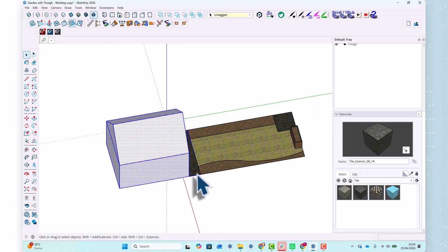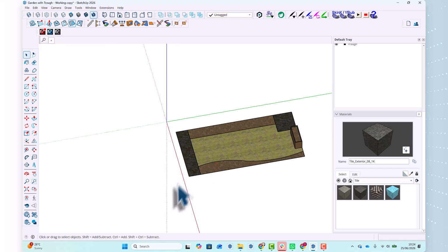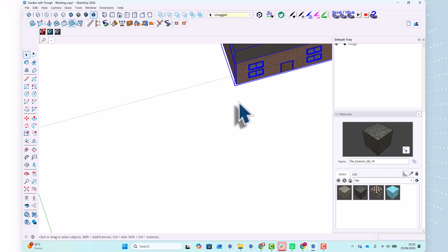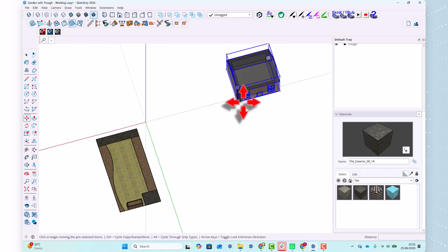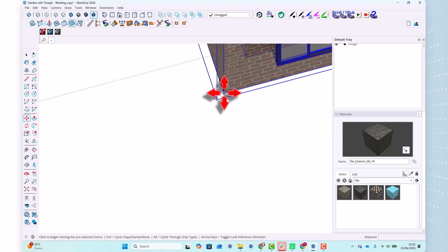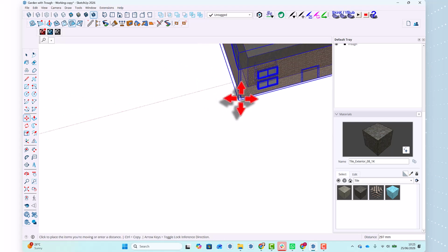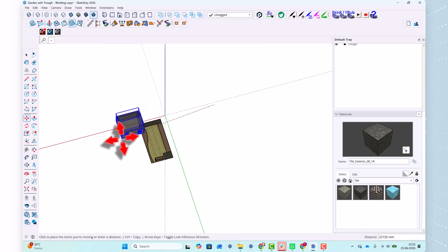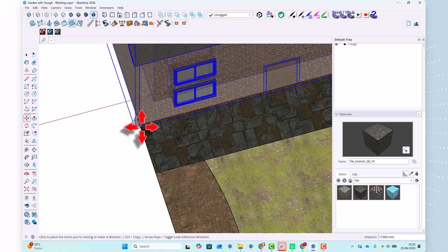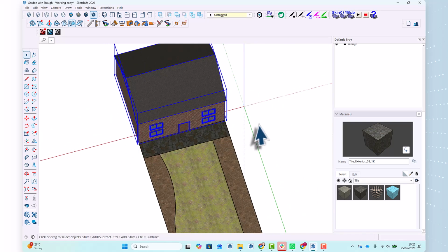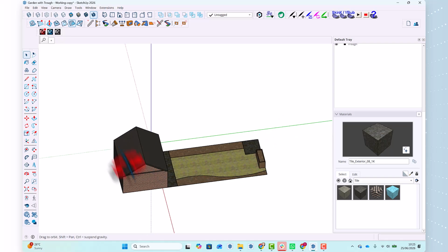I just want to deselect that and delete everything there. Now I'm going to move my house, and just recapping on how the move tool works: you press M for move. First of all, you select an object. So we select the house, press M for move, and then you click carefully on the point that you want to move, just once, and now the mouse is hanging onto that, and I can zoom in and out. I'll zoom into this corner here and click very precisely on that corner, and I have a house.